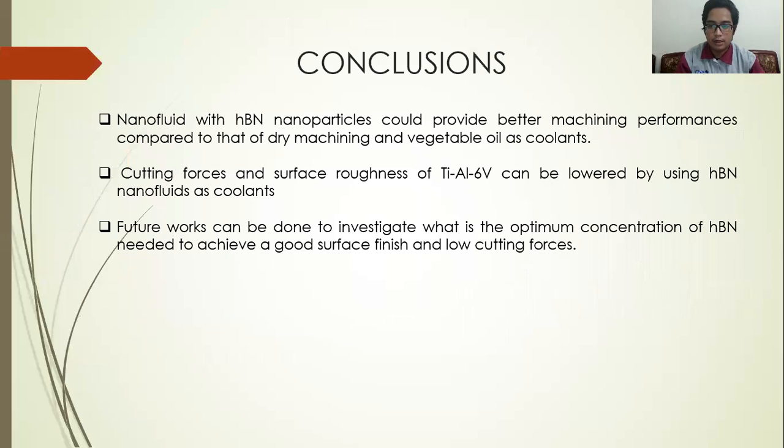For conclusion, nanofluid with HBN nanoparticles could provide better machining performance compared to dry machining and vegetable oil as coolants. Next, cutting force and surface roughness of titanium alloy can be lowered by using HBN nanofluid as coolant. My recommendation for this project is that future work can be done to investigate the optimum concentration of hexagonal boron nitride needed to achieve a good surface finish and low cutting force.